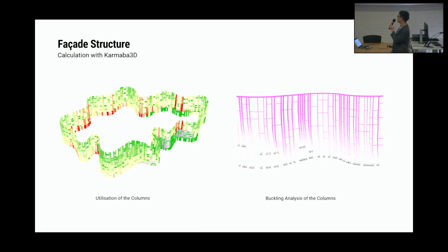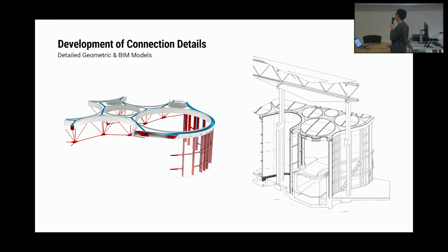So in the greenhouses themselves, they often have multi-story landscaping elements, which were designed as concrete. And that's why on the right, you can see that some of these supports in the middle or towards the bottom of the column are situated where we can essentially tie the columns back to these concrete elements and in a way reduce the buckling length of these columns. And so, as I already talked about, minimizing the impact of the structural elements was critical. We had to really detail all the different components together with the facade team to understand what is the maximum or minimum roof package that we needed, so that it could meet the architect's requirements.